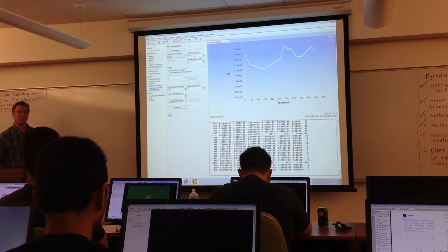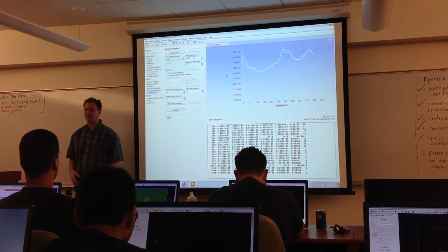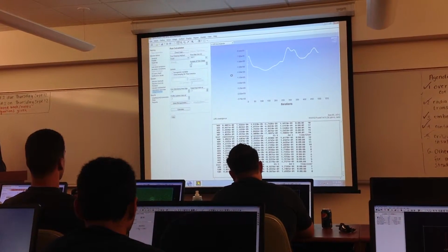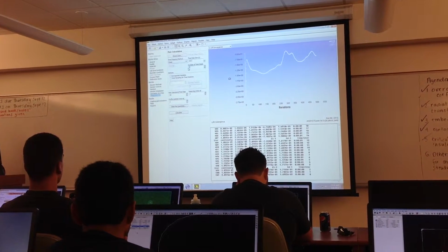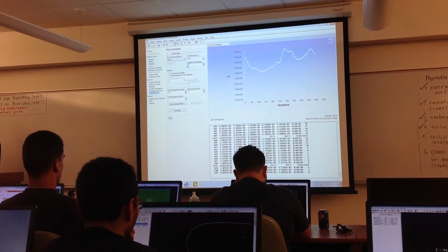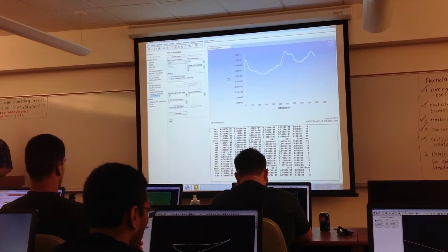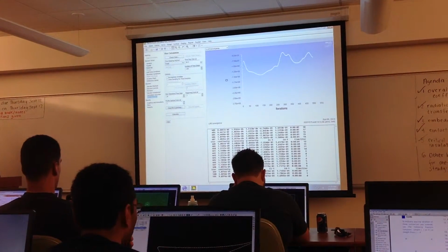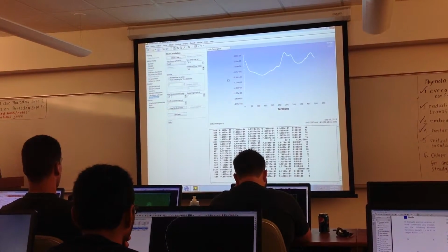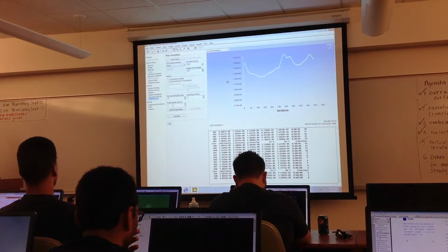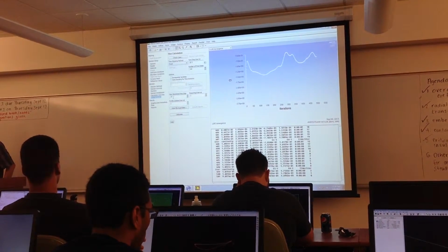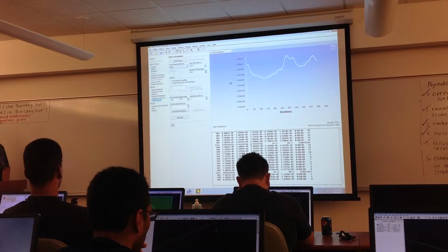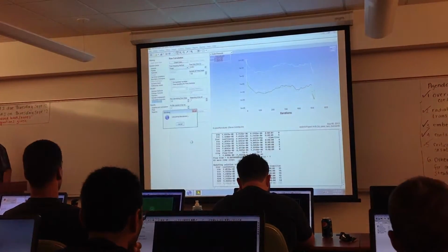The larger you pick it, actually, the better you might be able to kill the unsteadiness, I think, with a really large time step, because it's less accurate in time. And if you really want to resolve all the details, the true unsteadiness of the flow, you want a smaller time step, so you capture all the flapping of the wake behind the airfoil, if you were interested in doing that. So let's run 100 time steps for now. Iterations per time step: the rule of thumb is between 10 and 20, depending on the severity of the case. Let's say 15. Let's see how it does.